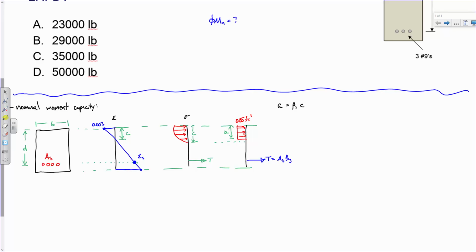Because remember we had some checks that the beam had to meet beyond just its capacity. There was a limit on the strain in the steel. Remember, the strain in the steel had to be bigger than a certain value. Do you remember what that was? We would compute the capacity, and then we would have to check and make sure that we provided at least the minimum amount of reinforcement.